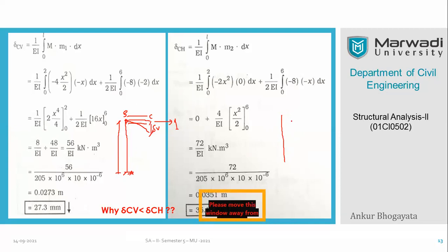The graphical explanation goes like this, because this deflection counts more. This is the horizontal deflection in this direction. You can see that the lever arm increases, the slenderness increases, the length also increases, even though the moment of inertia was double this.